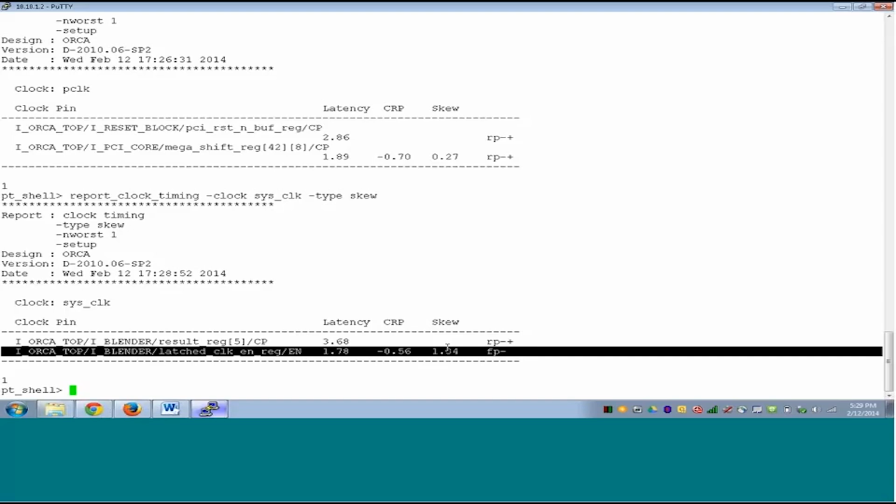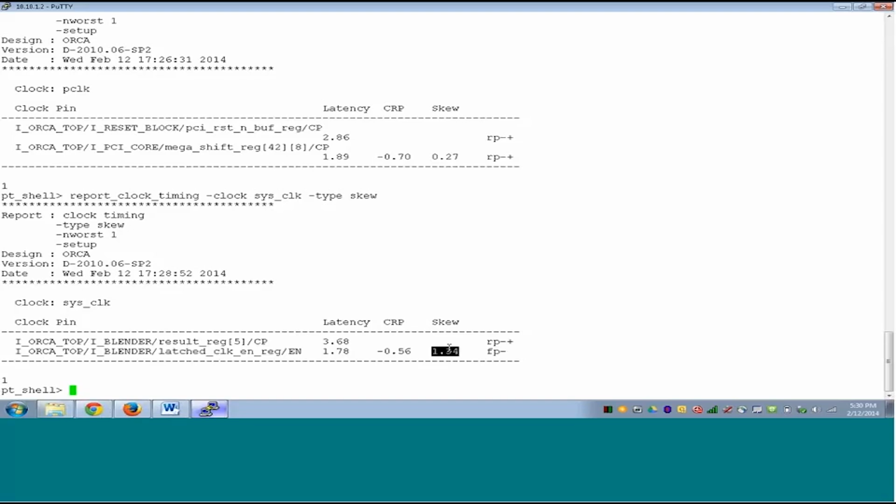The larger the clock latency means the larger the delay from the clock definition point to the flops. The larger the clock latency, the larger portion of the clock tree will be non-common. Increasing the non-common clock tree part will negatively affect your timing. So all the tools will try to keep lower and lower latency. So a clock that is generating a clock from a master clock, like a clock divider, need not be balanced with the rest of the logic. In such cases, you can see some skew numbers.